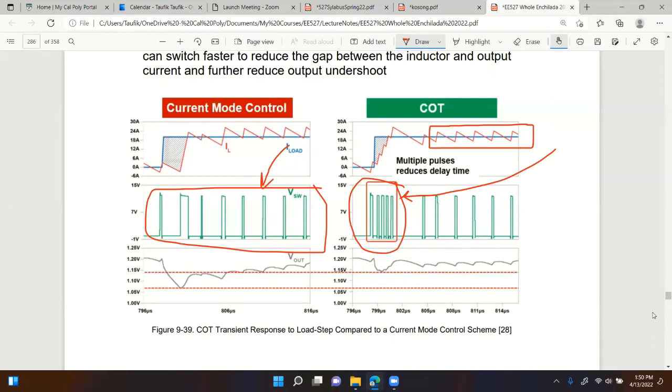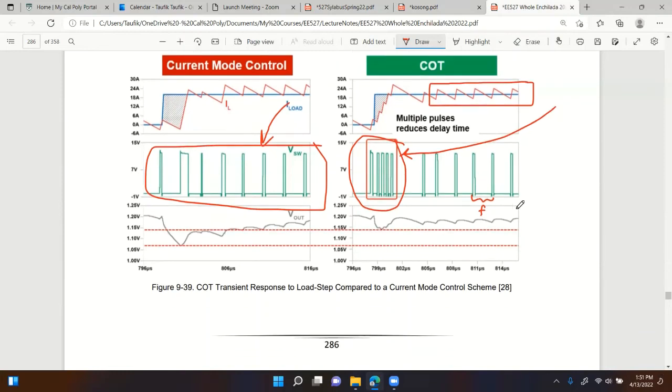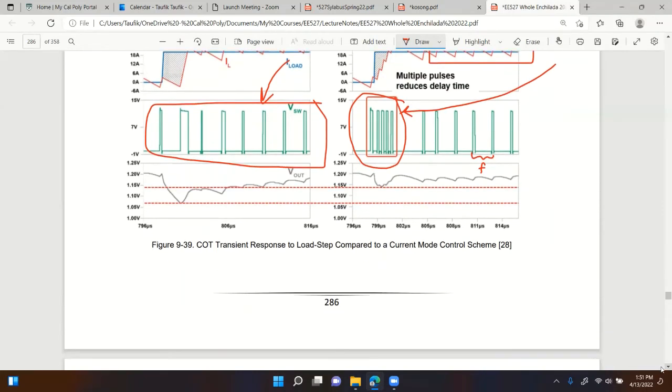What will be the lowest frequency you can tolerate, right? So that would correspond to this constant frequency right here, right? So the lower the frequency gives you the bigger value of the inductance, right? Okay. So yeah, design and component sizing in terms of the inductor would be a bit trickier than current mode control. So this is no longer PWM, right? On the right. Any questions?